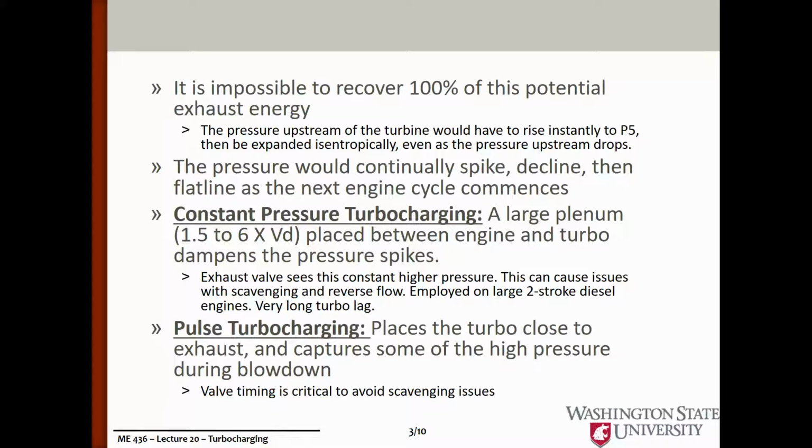Now, it's impossible to recover 100% of the potential exhaust energy. You would need the pressure between the cylinder and the turbine to rise instantly. So you'd basically have to have that turbine fan directly next to the engine with no volume between them that takes time to pressurize.